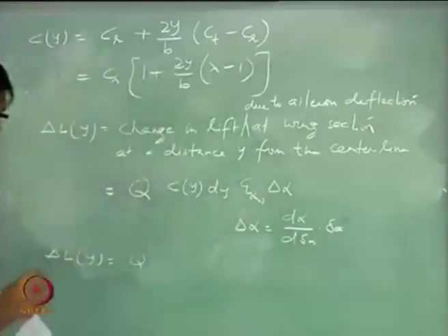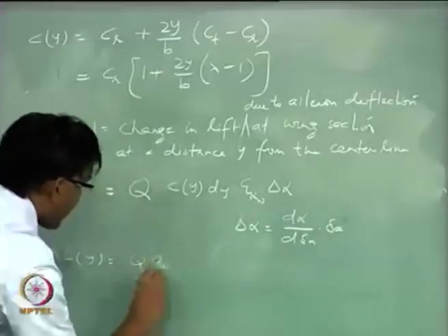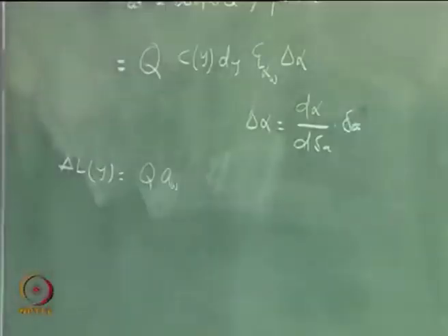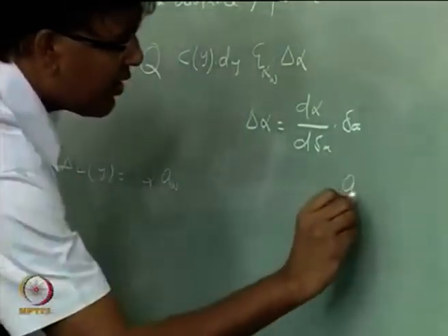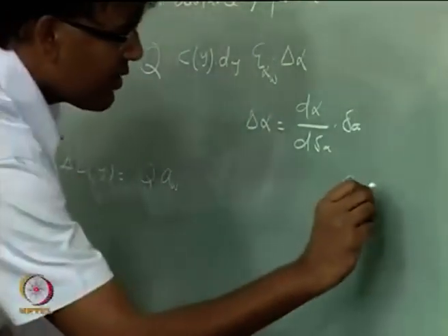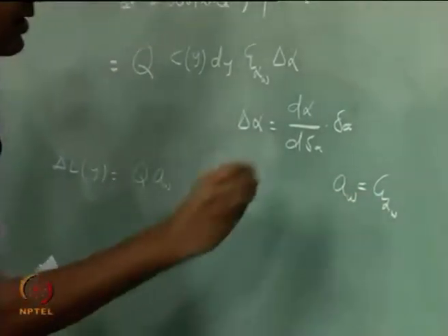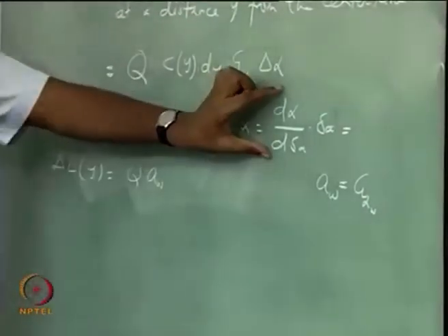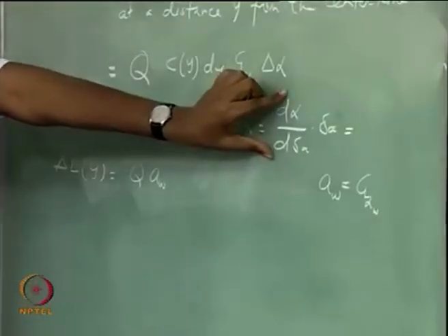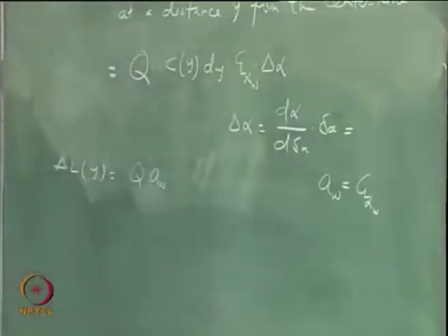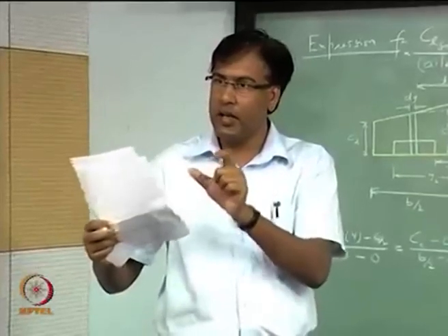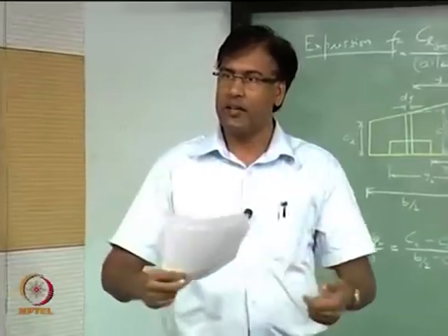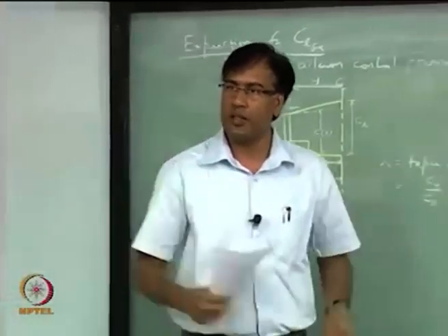So, I can also write this as AW. What is this quantity? It's like aileron effectiveness parameter, isn't it? And it will depend upon the surface area of the aileron as compared to the area of the wing.